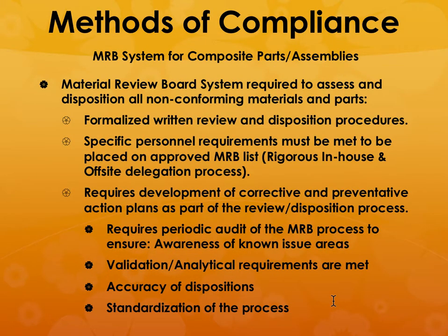And there is something called a material review board that is established at each vendor or the final component or final system manufacturer, and they get together and they are required to assess and dispose of all non-conforming materials and parts.